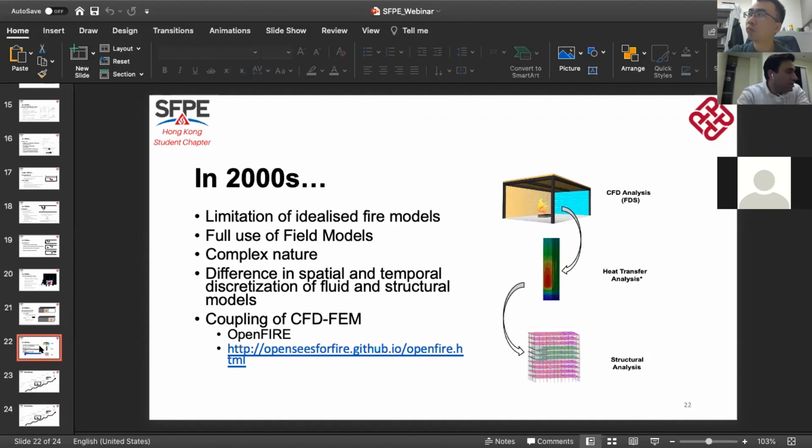You just take the temperature, for example the adiabatic surface temperature, and do a simple heat transfer analysis using these models in OpenSees. For steel, we can take only one temperature on the surface, but if you have concrete, you might need to put more thermocouples inside.